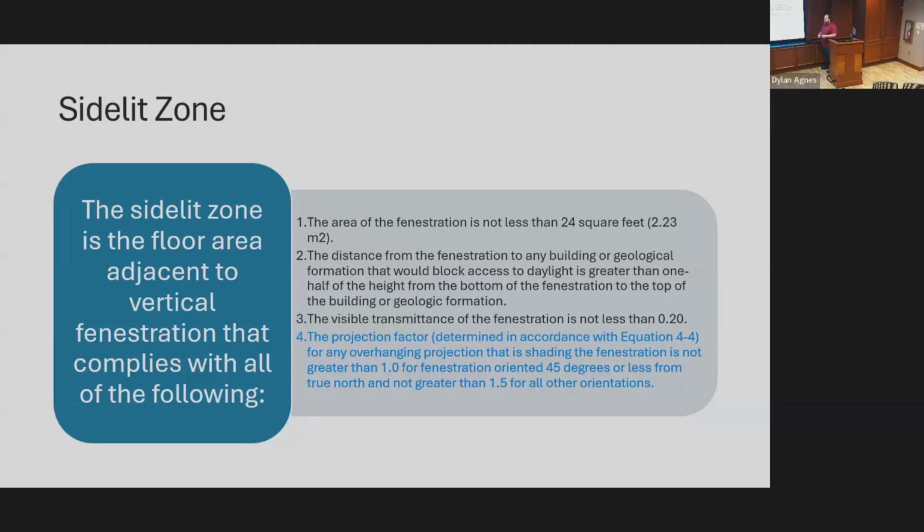The projection factor comes into play. Dr. Woods talked about that earlier, about the building envelope. And so this deals with overhang, right? So the projection factor was a way for you to increase your vertical fenestration, your window to wall ratio, right? But you would not be punished, or I guess say not punished, but compensated later on down the code compliance that, you know, hey, I reduced daylight entering my building to reduce my solar heat gain coefficient so I can get more glazing, et cetera, the impact on my heating and cooling loads. Oh, by the way, it's still fully daylit though. Even though I'm blocking out that sun and taking the reduction in the loads, it's still daylit. You don't get to do that in 24 anymore.